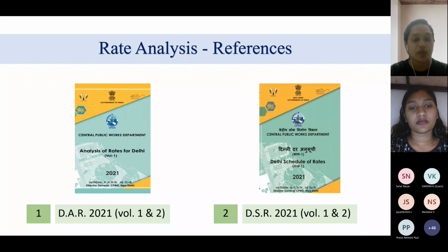There are such instances where we are dealing with the same work, that is brick masonry work, but based on the material we are having two different types of estimations, that is estimation for brick masonry and estimation for rubble masonry, wherein the rate is the varying part, not the quantity. So estimation as a whole, we cannot say it's a fixed thing. It will depend on which resource or material you're using. If you're changing the material, the rate analysis changes, and in turn it will affect the estimate.